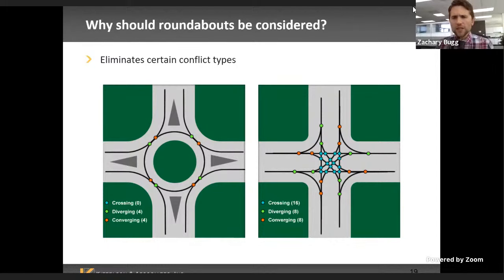And the conventional four-way intersection shown on the right there, regardless of whether this is signal or stop control, the conflict points are the same. So what you see here is you got 8 conflict points at a roundabout versus 32 at a traditional four-leg intersection.